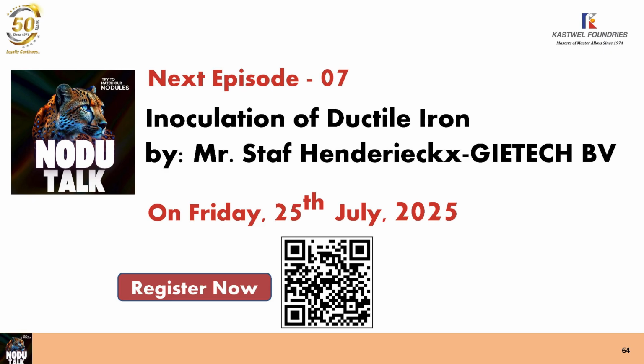But the second thing, and that's something I have always been fighting on, is your first metal that enters the mold. What is your first metal? The first metal is the metal that enters the mold before the whole pouring system is filled. If you have your sprue, the metal falls down, and as it falls its section decreases until the bottom. During the decreasing of the section, it continuously absorbs oxygen.